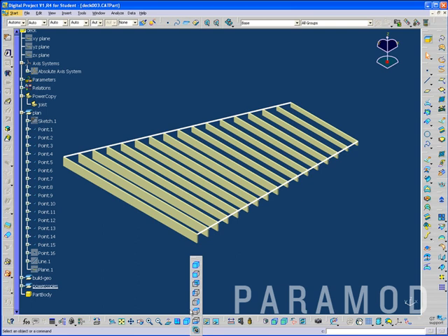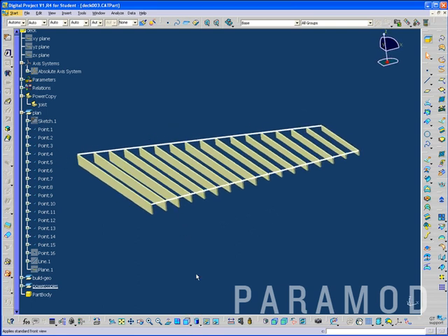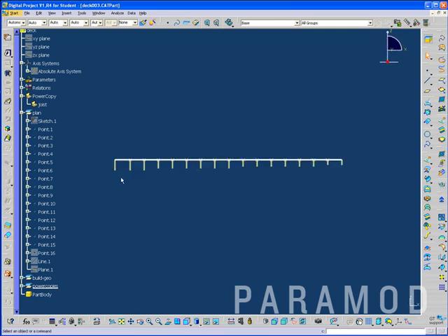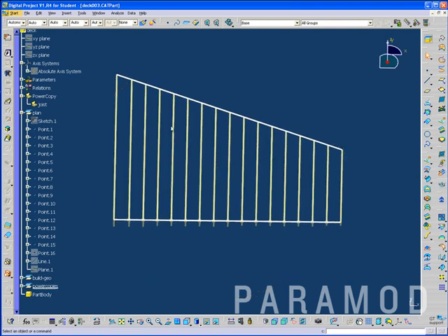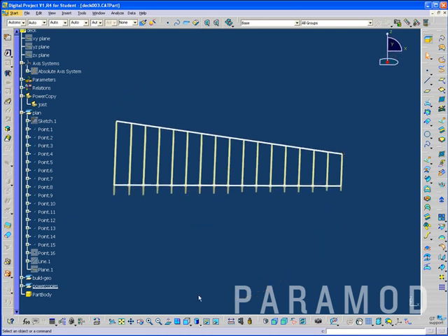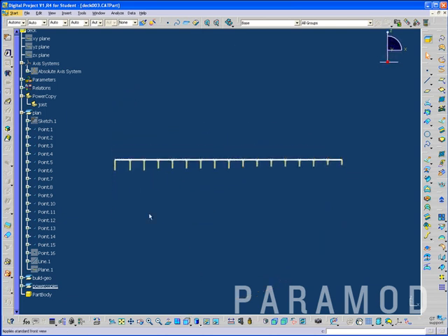And this is one example that I use where if we were thinking about lumber and spanning, we wouldn't want every piece to be a custom size. And so what I've done is I've created a rule based on how far something will span, which will set up how deep that member will be. And so we can see as we move across, we've got a range of a 2x12, 2x10, 2x8, and then 2x6.